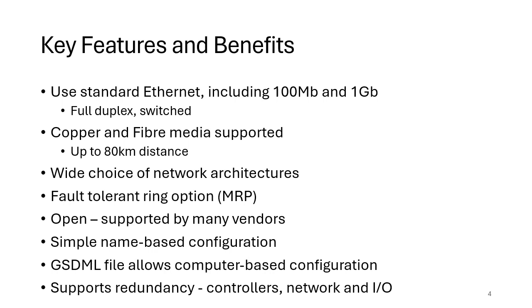In theory, it is human readable, but the idea is the GSDML file allows your configuration software to understand what the capabilities of your I/O device are, and that includes all of the I/O modules that might be plugged into the I/O device, along with all their configuration capabilities. But what it means is, in order to interoperate an I/O device with a controller, the GSDML file comes from the vendor of the I/O device. You use that with the vendor who makes the controller's software in order to configure the device, and then it should all work.